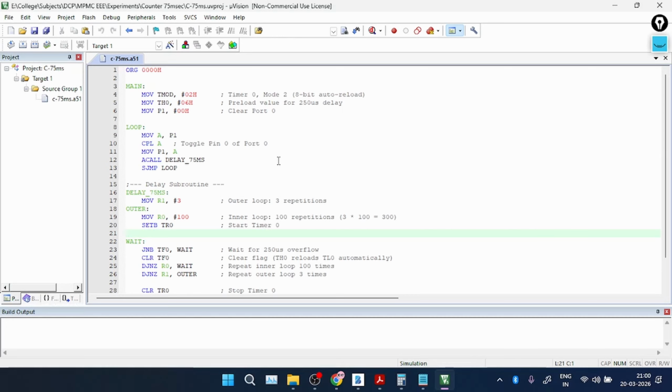In a virtual setup, I won't be able to update the 8051 timers using T0 and T1. That's why I have moved to the timer. It's the same program, only the TMOD initialization will be different. Other than that, there is no difference.